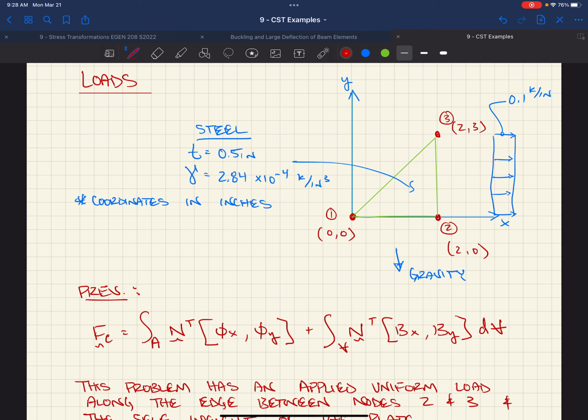So we had a point load and a uniform load, and we evaluated that point load and the uniform load based on their overall contribution over the entire element, okay? A uniform load acted over the entire length, so we had the integral, we had to sum up essentially all of its individual contributions. And as you all got from that homework, the point load is essentially a uniform load just at one discrete point, right? And so you could just evaluate the shape functions at that given point.